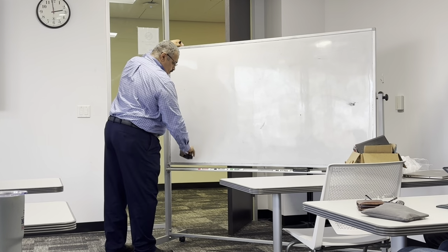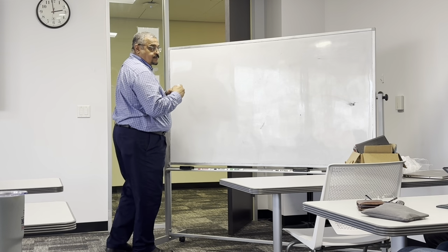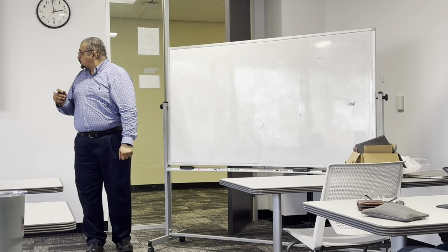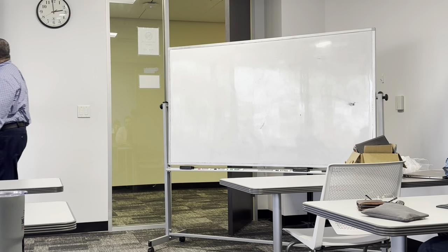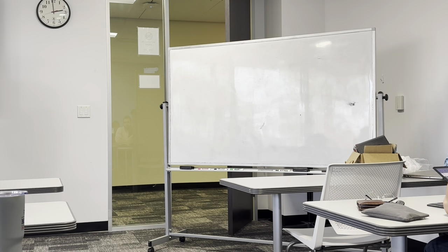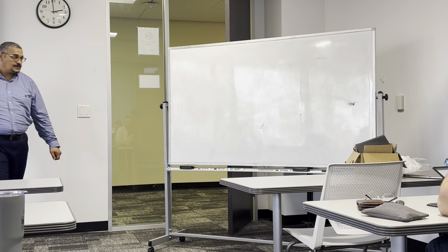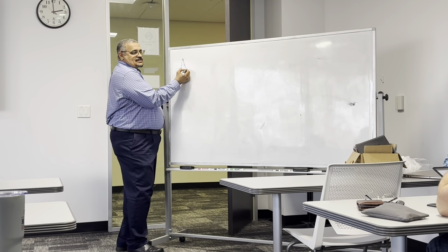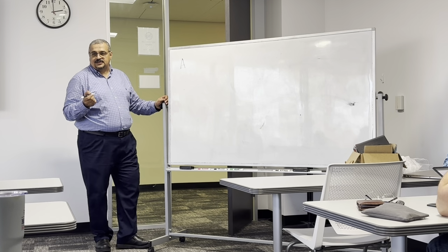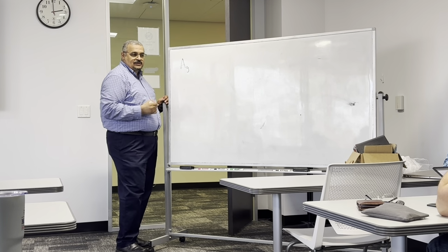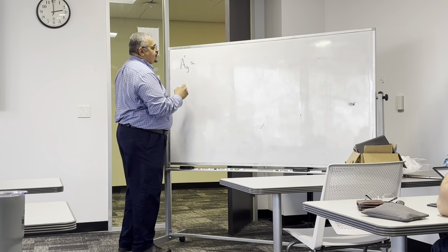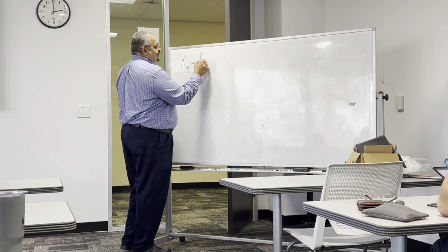There's at least one component I think you could omit. I see at least one component you can omit from this: RO1 in the center block. RO1, this one? Yes. So this voltage is the same as this one, so RO1 has no effect. So the gain, and what's the nature of this gain? It's a transconductance, right? So we should call it AG, transconductance, and prime. What's the output quantity? It's a current, right?